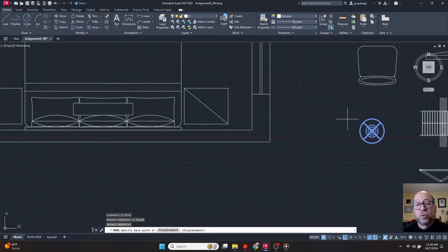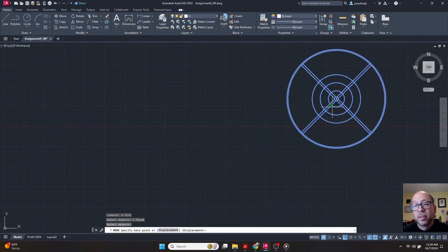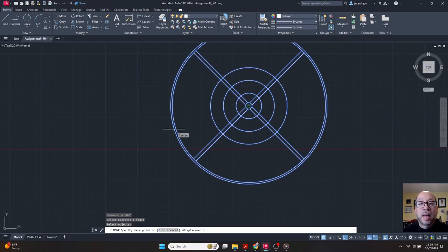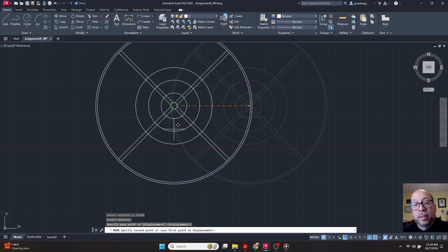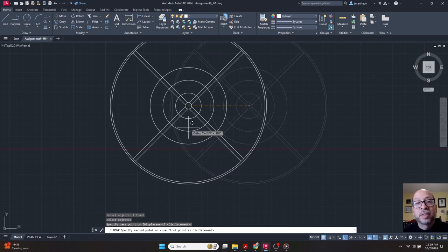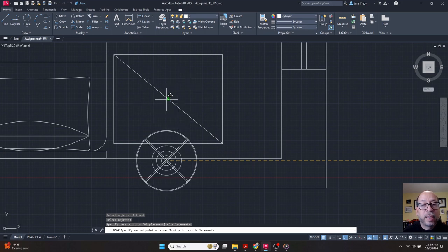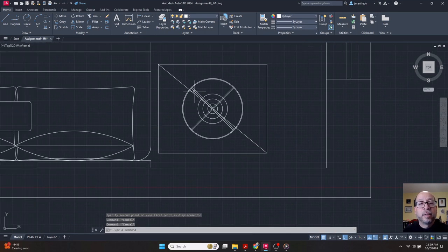This is a circle. So circles have the center snaps. So I should be able to locate the center of this object. And if I hover along this curve here, a little green circle appears in the center of that lamp. You see it here. So by clicking on the object, AutoCAD recognizes it's a circle, and circles have centers. So if I click on it, it'll snap to the center of that circle. I take that and move it to here, to the midpoint of that table, click, and then hit escape.